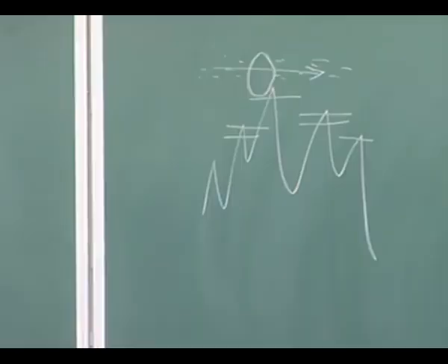When these abrasive particles come in contact with the workpiece surface over here, they remove the peaks one by one, and the finishing keeps on improving, and you can easily get a surface finish of less than 10 nanometer in this particular case.